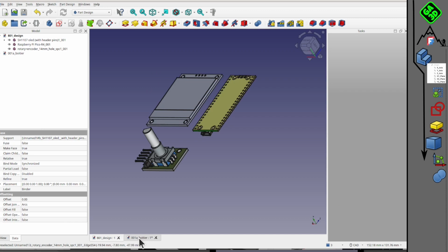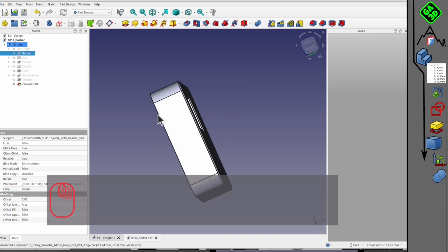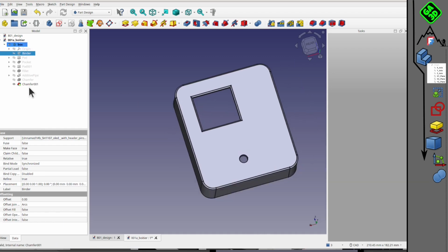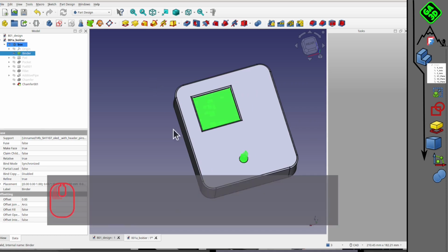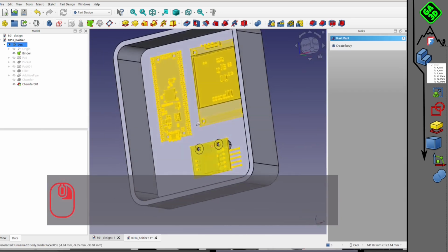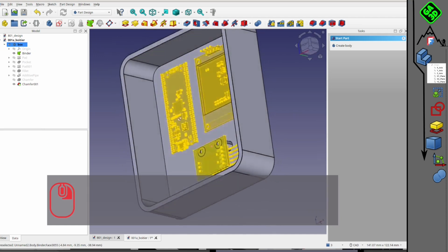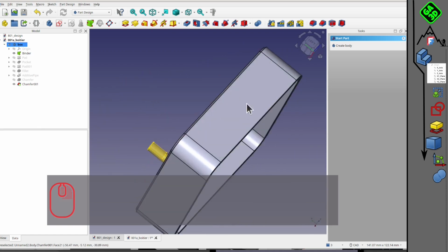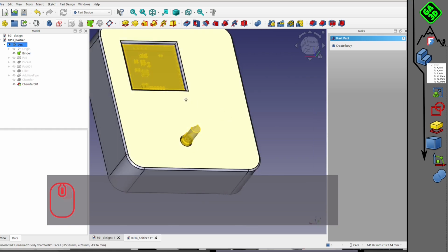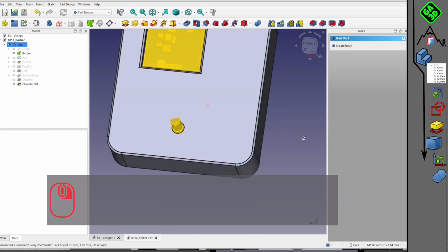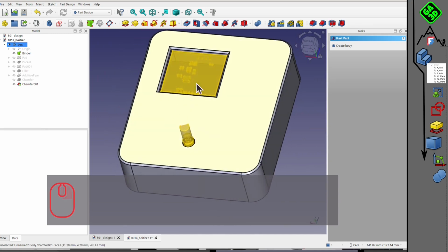But at the beginning, in addition to the body, we create a shape binder, which is based on external elements. So in this way, we know where the elements are to be integrated, what we need to take into account when building our part. And we can actually use these elements for our construction, to position sketches, use them as external elements. So that's what we did here.